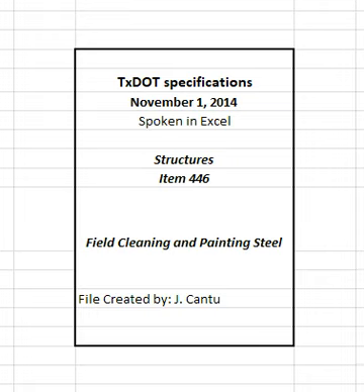When using power hand tools for spot cleaning only that are equipped with high-efficiency particulate air, HEPA, filter vacuums that will capture all removed paint, rust, and other debris. Otherwise, provide an airtight membrane below the member being cleaned to collect all falling debris. Provide a system meeting SSPC Guide 6, Class 1W, when using water blasting.